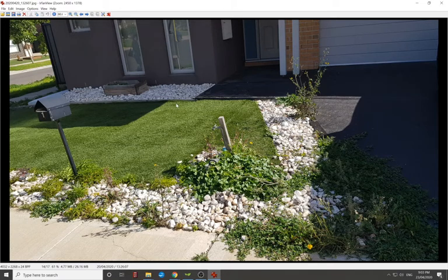We're going to bring the path out probably from that about 600 mil out from there, and about a meter wide path, and it's going to come around and meet back around to the side gate, and that way you get a bit of garden here. You reduce this lawn area, so when you do this area here, which could be either all lawn, genuine lawn, not the fake lawn, or pebbles, because we might reuse these pebbles as all pebbles, because we're trying to keep the cost down here.